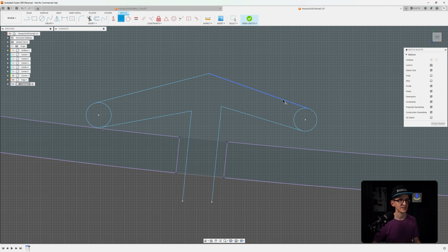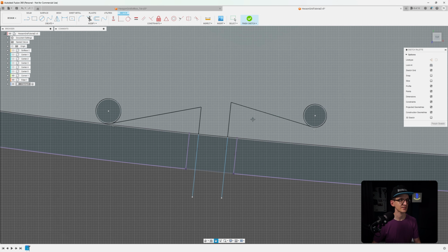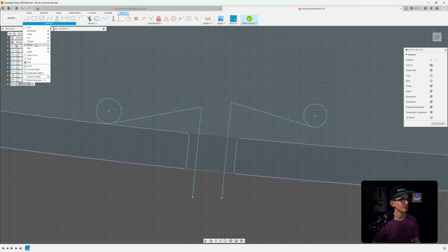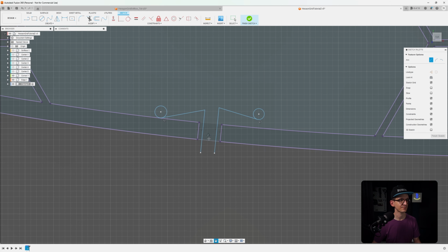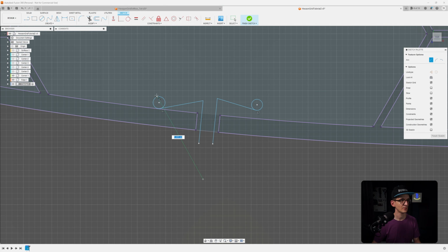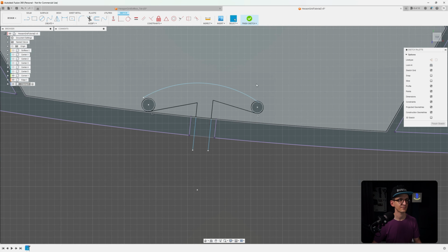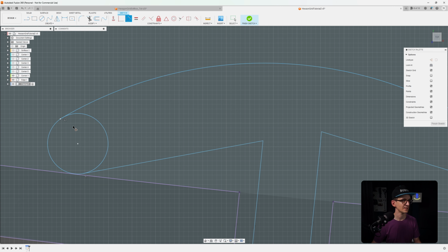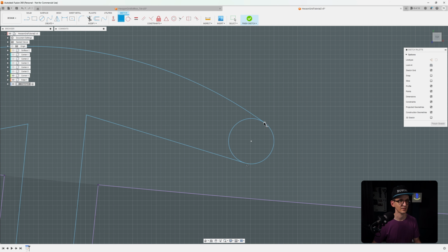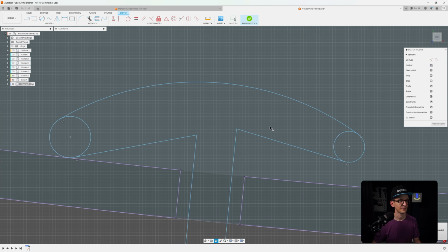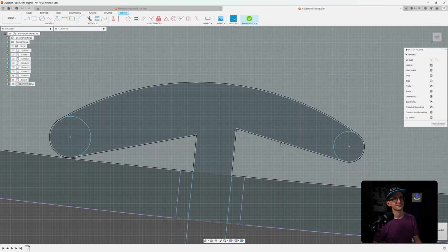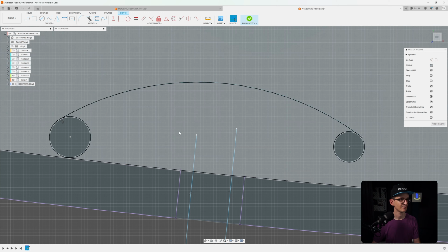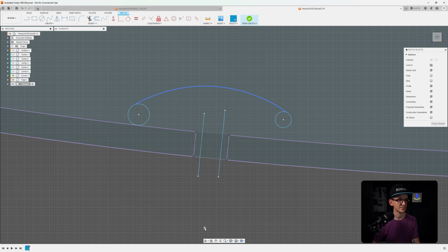And it would be nice to have this as an arc. So get rid of those lines again and go arc, right? Center point again. Center point can be somewhere here. And then we go kind of here to there. And then we constrain it correctly. So this is tangent. This is tangent, but it needs also to be touching the, okay, and I think here it's actually already doing that. Exactly. This line, the same, referencing the same center point.